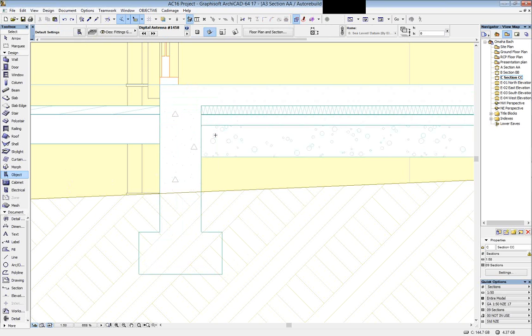So if we want a volume of, how much underfloor insulation do I have, it's actually giving me the correct volumes. If I change the width of that perimeter beam, it changes the volume of insulation, sand blinding, and hardcore fill. So this is proper BIM. If you do use ArchiCAD's powerful scheduling to schedule out quantities, it's doing it correctly. So this is great for those that use ArchiCAD's powerful scheduling.